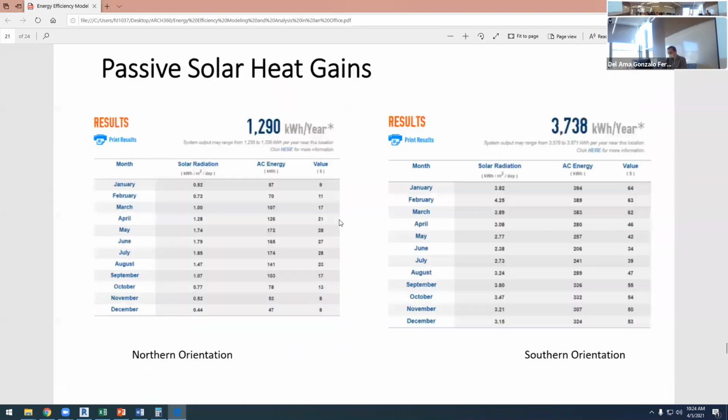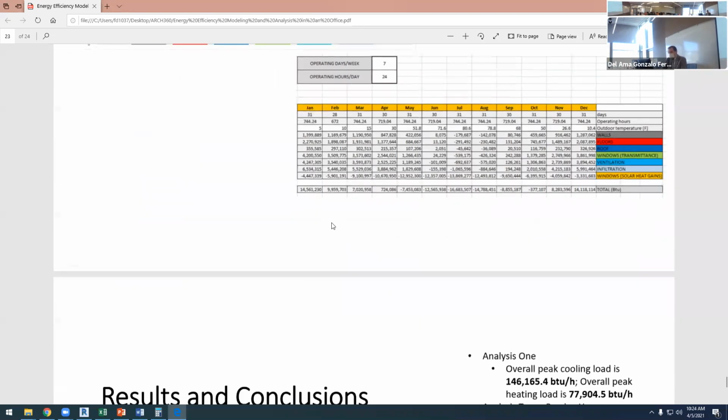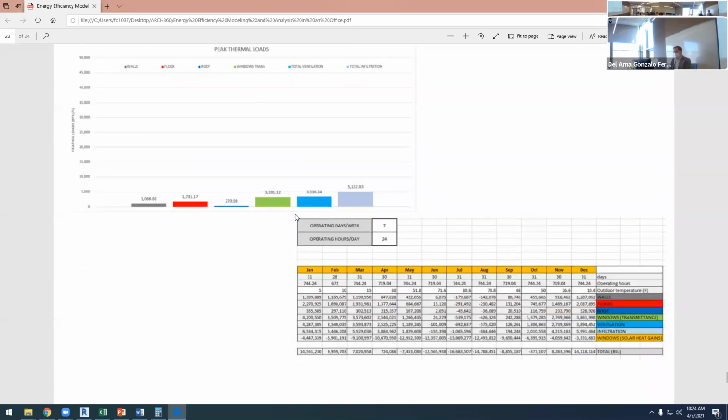Okay, but basically the conclusions that I can reach looking at this graphic is that you have selected passive house standards for the envelope. You have a triple glazing. You have controlled the heat recovery with the ventilation. So what matters the most is the infiltration. And even if you have a tight construction.